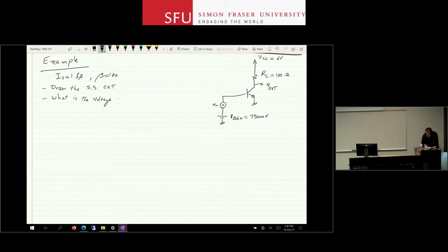So I'm just going to, on purpose, drop the small signal from here because I want you to keep that in mind, that when I talk about voltage gain, when I talk about input resistance or output resistance, or anybody else talks about these parameters, they're only considering the small signal, not large signal, right? So the DC component is out.